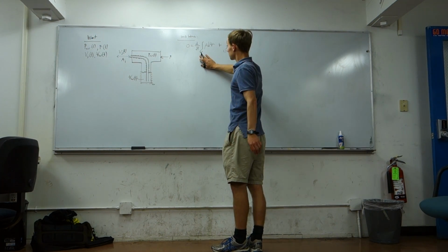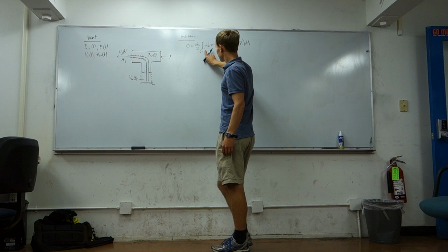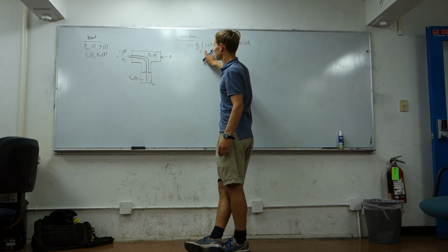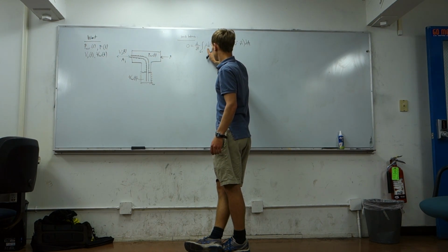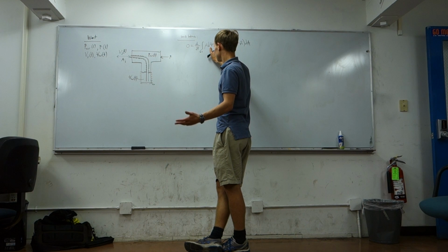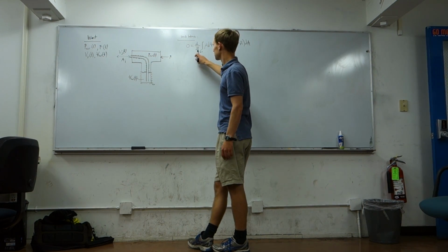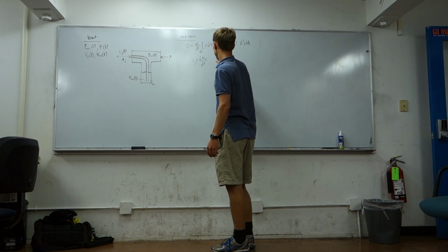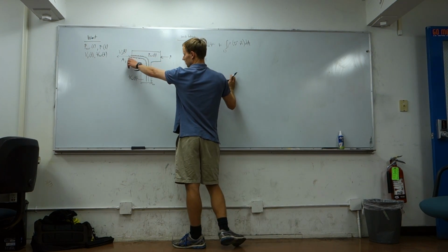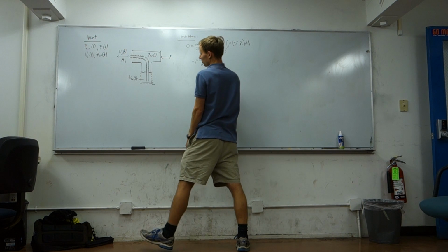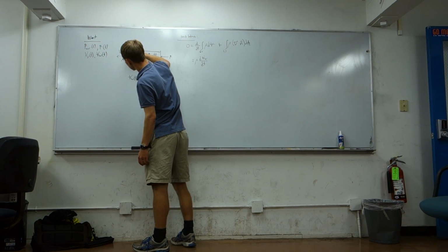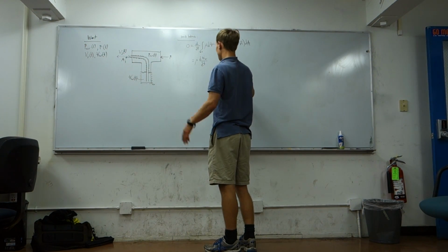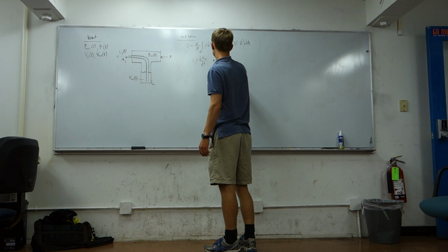Okay, so our term inside here, rho for our water is going to be uniform in the volume, so that comes out. And we're left with the integral dV, which is just V. So rho will also be constant in time, so this becomes rho times dVw dt. And our flux term, we only have one flux term, it's going to be an outflow, and the normal vector is in the same direction as the outflow. So it'll be a plus rho Vj Aj.